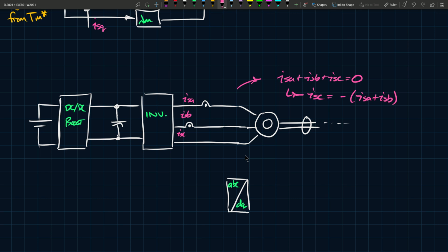So that's convenient. What we can do then is have this current go down. So this is ISA. We can have this one also like this, and this would give you ISB. Then you can take the two of those currents, pass this one here, pass that one here, and you subtract the two, and then you get ISC.